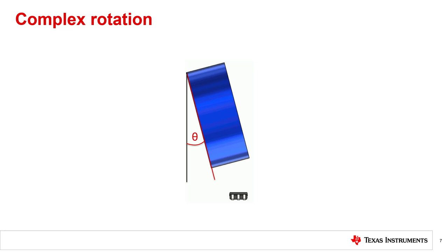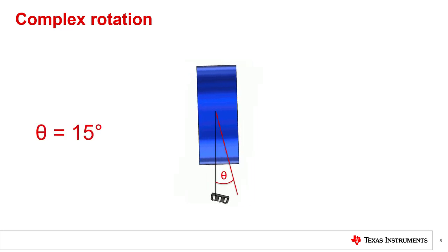Let's imagine the tilt of the magnet about its own center by about 15 degrees. If we rotate our perspective back by the same 15 degrees, the magnet appears to straighten again, but our sensor is now offset and tilted from its original position. If we duplicate our sensor in the TI Magnetic Sense Simulator, we can place our second sensor at this new location so that we can observe the behavior of the magnetic field for both the vertical case and when the scroll wheel is tilted left or right at any position.